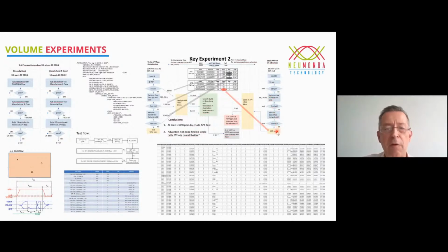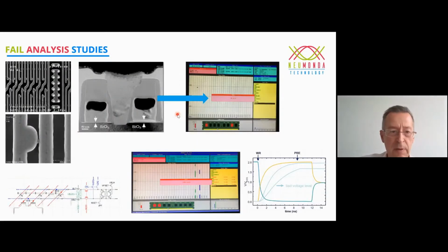Oops. And many of those proven fails in application in motherboard are not found by the classical flow. So you can make a lot of cross experiments. What is your quality? What do you gain? What do you lose? And for this, you need a pilot factory, because such experiments need 10K or 20K components if you want to sort out 50, 100 ppm events.